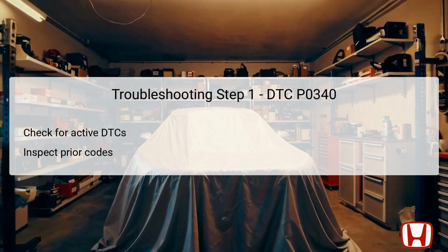The first step in troubleshooting the DTC P0340 involves checking for any active diagnostic trouble codes, DTCs. This is crucial because it provides a more comprehensive understanding of the vehicle's current condition. If there are other DTCs present, such as P0335 or P0344, these may indicate related problems that could complicate the diagnostics.